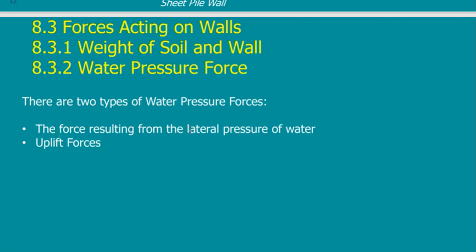The force resulting from the lateral earth pressure, which is what we are going to study in the next part of the lecture, is the lateral pressure of, not the lateral pressure of the water, sorry, we are going to study the lateral pressure of the soil. I'm sorry, I confused it. But for water, of course, water has pressure in any direction: sides, up, down, in all directions. So there are uplift forces on my wall, and there are horizontal forces on the wall.